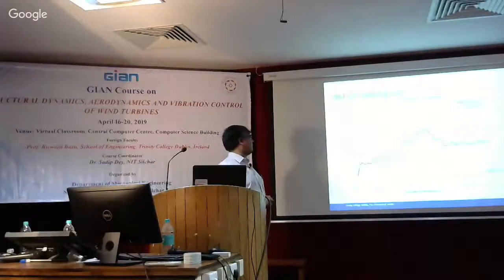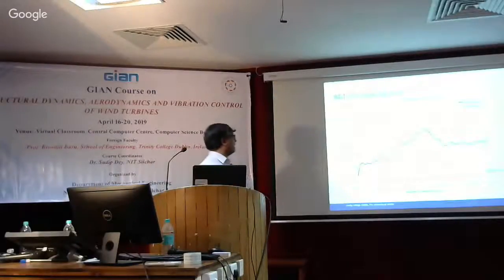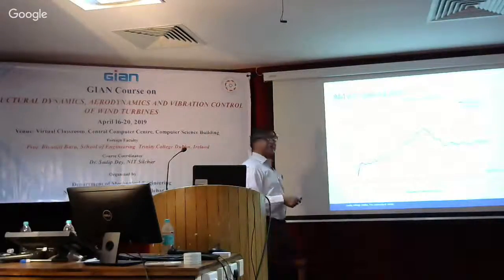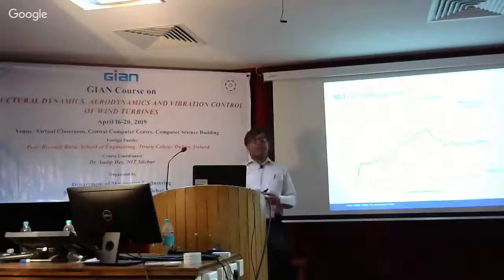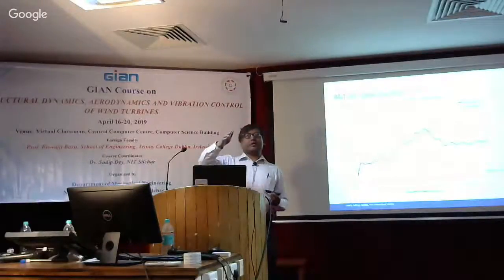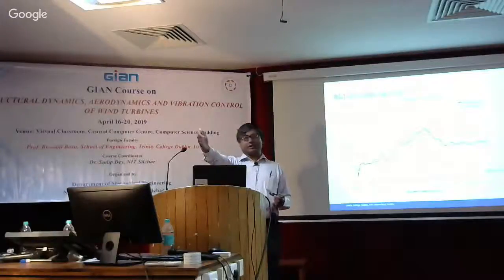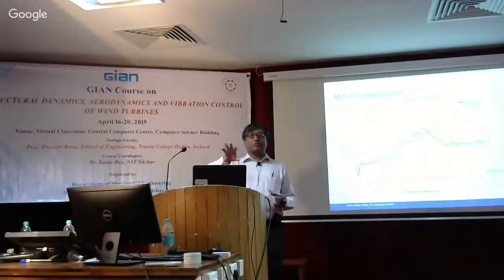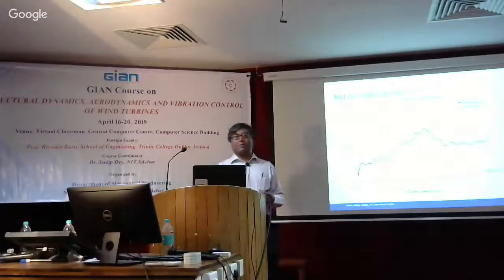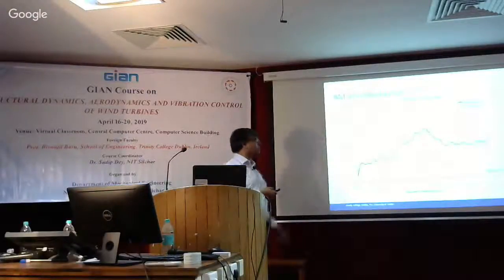So I'm going to skip this very fast. And again, you can control the blade bending moment as well, because obviously, if you can feather it out when there's no load at all, and you have a full load when it's facing the blade, there must be some position where you can actually control the load to a desired value, and that will change your bending moment as well. This is exactly what we've done.